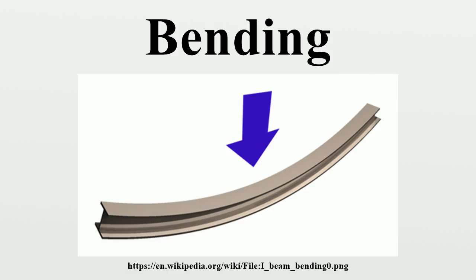After a solution for the displacement of the beam has been obtained, the bending moment in the beam can be calculated using the relations. Simple beam bending is often analyzed with the Euler-Bernoulli beam equation. The conditions for using simple bending theory are: the beam is subject to pure bending. This means that the shear force is zero, and that no torsional or axial loads are present. The material is isotropic and homogeneous. The material obeys Hooke's law.